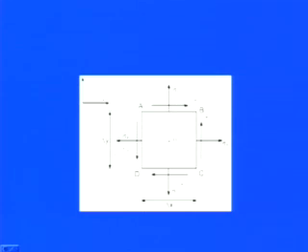So these 2 components, sigma x and tau xy, are working on the sides of the element in the x domain. Similarly, the other 2 components are working in the y direction, like sigma y in the vertical directions. Both go in opposite directions and maintain the equilibrium around the point A. And similarly, we have tau yx and tau yx, because we are working in the y domain, and x because they are going parallel to the x direction.